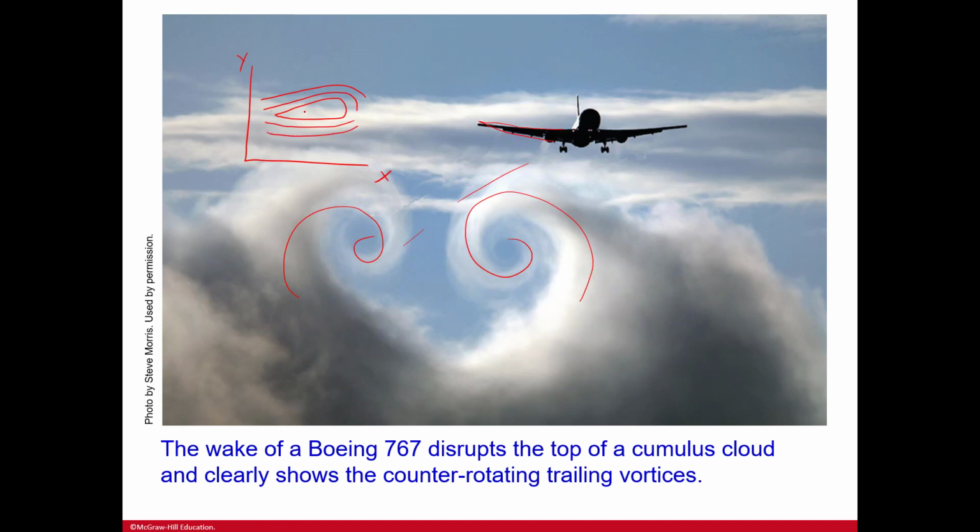And so for drag and lift, they're computed and looked at very differently, but on a surface level, like an XY plot, they look very similar. And so you will have this force here, and then because of that, you'll have these streamlines going the opposite direction, right? And so you will have both of those happening at the same time. So you can think of this as a stationary body with just drag happening over and under. And so you can see the after effects of this disruption.